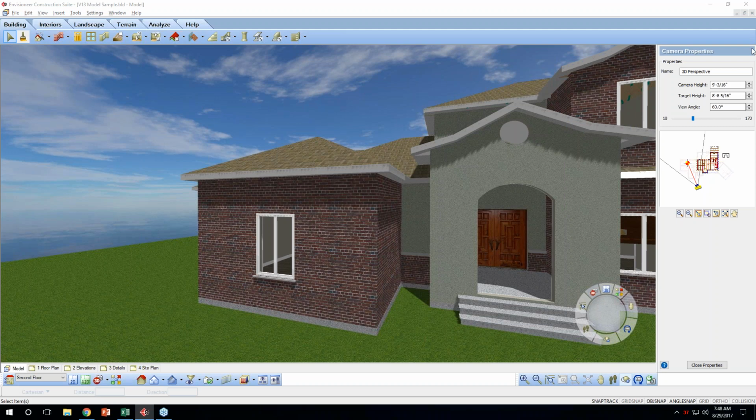Does the truss function recognize the hip configuration and saddle trusses over a truss run? When you're looking at the trusses itself, it's going to be looking at the surface above and the surface below it, meaning that it's going to look at the shape of the roof that you're placing it on with the truss run function,